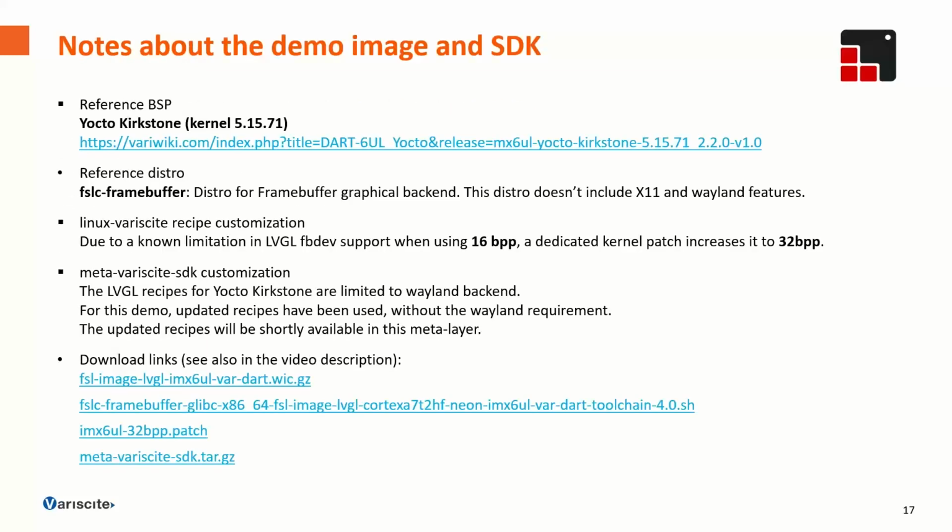Just a few notes about the SDK. We used the latest Yocto Kirkstone SDK available for the i.MX 6UL. Here you can find the references. As I said before, we used the FrameBuffer backend because we don't really need either X11 or Wayland.